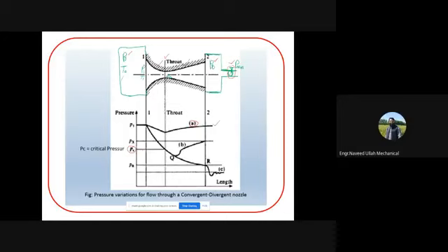And then after that, if you look at this case, where there is some px value, any value, two values are there, right? So px and pr, two values are there. So if you compare these two values, what is the px value? Basically this is the value of the back pressure. This is one value of the back pressure and this is the other value of the back pressure, right? It means you can say this is your pb, you are decreasing the back pressure.